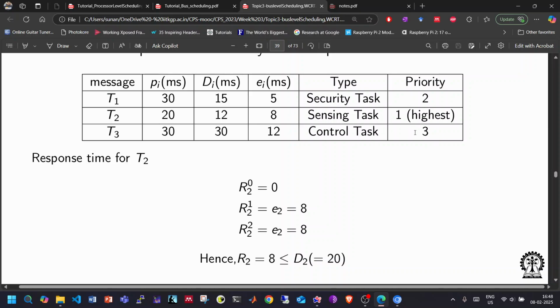This is to give you an easy example. Here dynamic priority is not considered, fixed priority is considered, and we are trying to find out what is happening. In case of dynamic priority, if we are considering a set of tasks to schedule with dynamic priority, then we have to find out for all feasible priority allocations, meaning those priority allocations for which deadlines will not be missed, I mean, there is a valid EDF schedule, what is the maximum response time. That maximum value will be considered as the worst case response time.